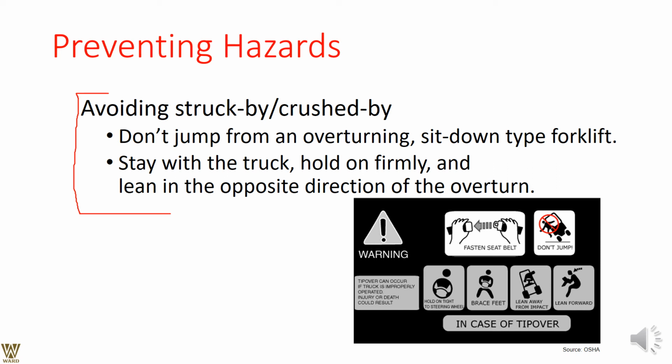Avoid getting stuck or crossing by. Don't jump from an overturning sit-down type forklift. Stay with the truck, hold on firmly and lean in the opposite direction of the overturn. Now this is what we need to go around here. This is what we are supposed to follow.